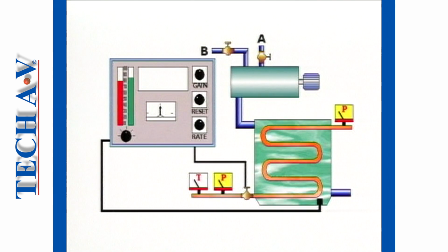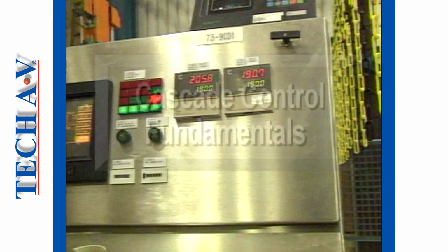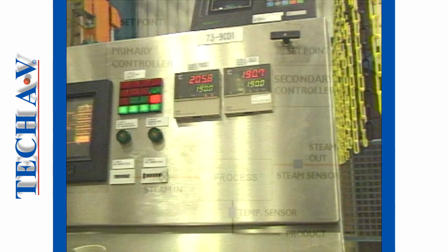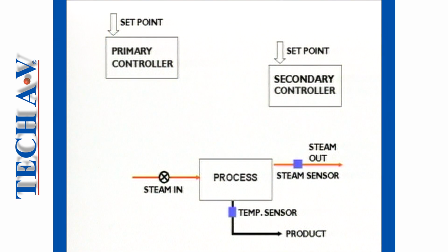It was realized that steam pressure was the process variable they could effectively use to speed up the response of the system, since changes in steam pressure always produced variations in steam temperature. This was a case for cascade control. The fundamental principle of cascade control is to use the output signal of one controller to adjust the set point of the second. Let's explain.